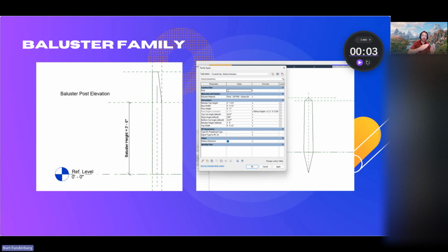So I can change the bevel angle, I can change the extension, I can change the entire height, and that's all based upon the design architect's direction. So I'm trying to build these so that if the design can change and they want it to change, it can do that without us having to make 5 or 6 different families and constantly change them out. You're just having to change a value and then see how that looks.